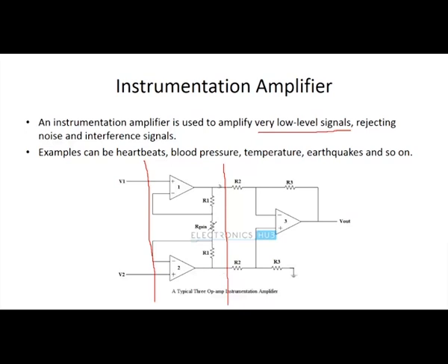Then you will be having two voltages at these two nodes, and that is the actual voltage given to the differential amplifier circuit. And we know that for the differential amplifier circuit, again using the superposition theorem, keep V1 dash 0, apply V2 dash and calculate the voltage at this node and find out the output. Again for the next case, keep V1 dash given and V2 dash 0, obtain the output, and finally add the two output voltages to find out the output of the instrumentation amplifier.